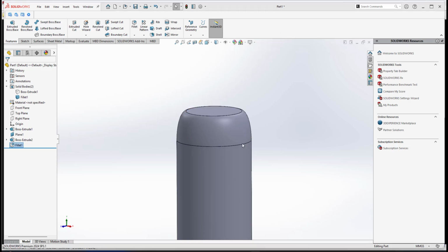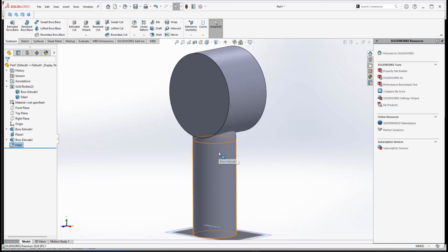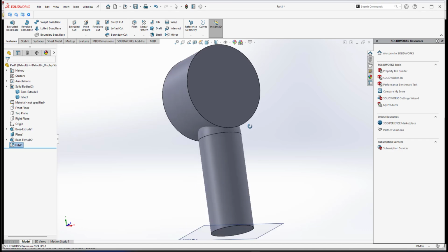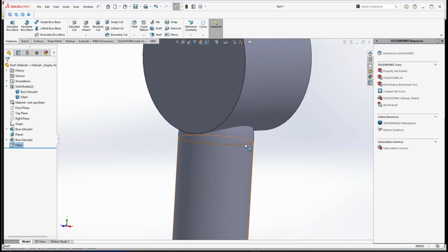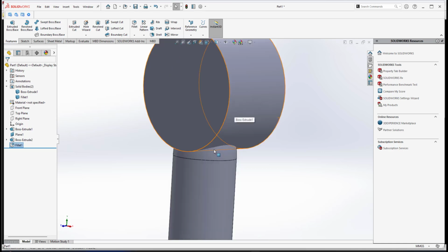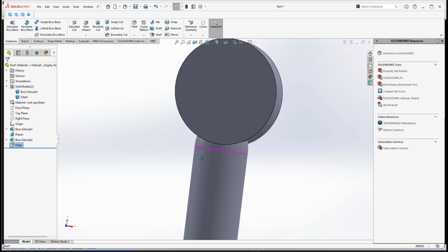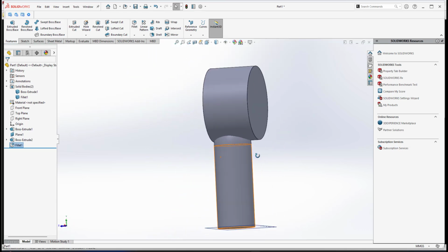If I exit isolate, then I have this shape, kind of more curve inside. That's why I don't merge it as one body. If I create a fillet at those edges, we cannot get this kind of shape, right? So this will be basically the shape of my